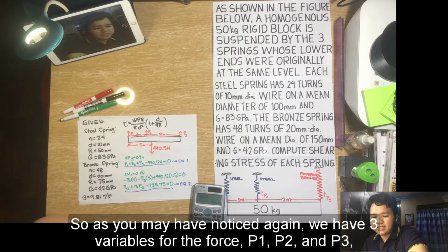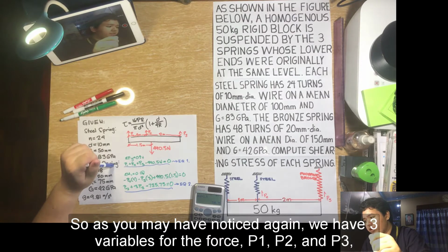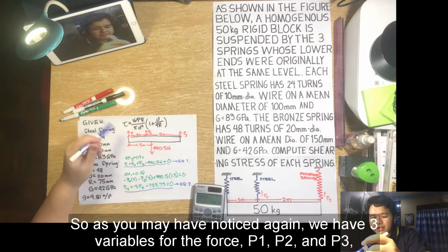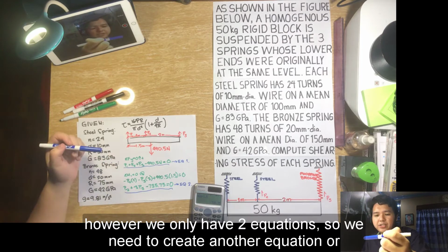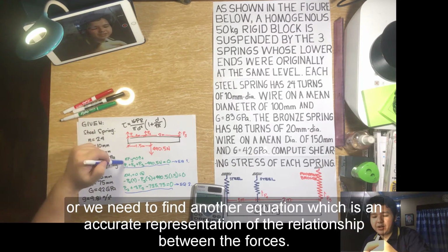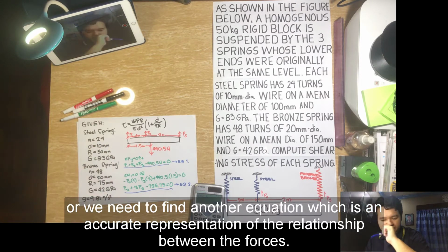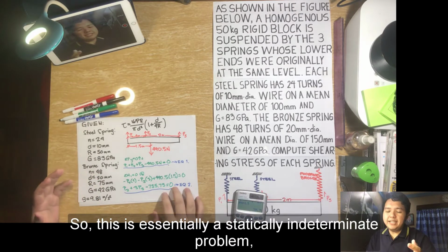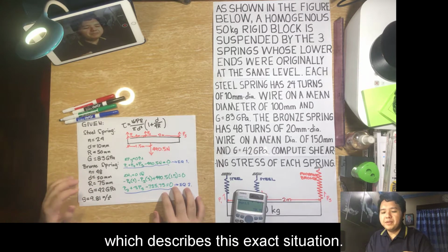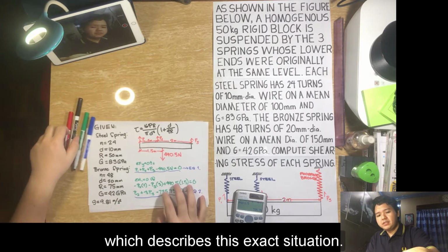So as you may have noticed, again, we have 3 variables for the force, P1, P2, and P3. However, we only have 2 equations. So we need to create another equation, or we need to find another equation which is an accurate representation of the relationship between the forces. So this is essentially a statically indeterminate problem which describes this exact situation.